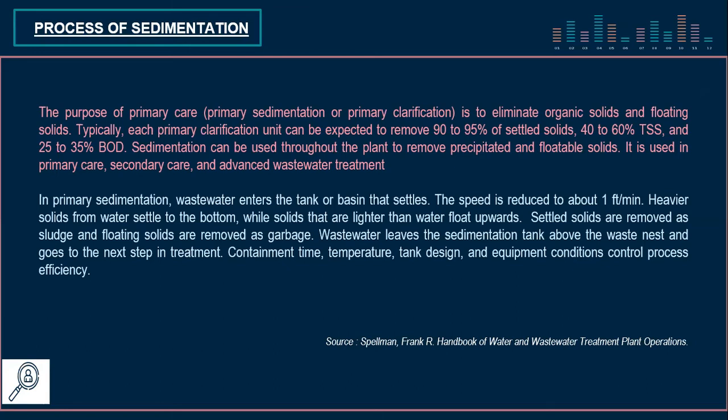Heavier solids from the water settle to the bottom, while solids that are lighter than water float upward. Settled solids are removed as sludge and floating solids are removed as scum. Wastewater leaves the sedimentation tank and goes to the next step in treatment. Contact time, temperature, tank design, and equipment condition control process efficiency.